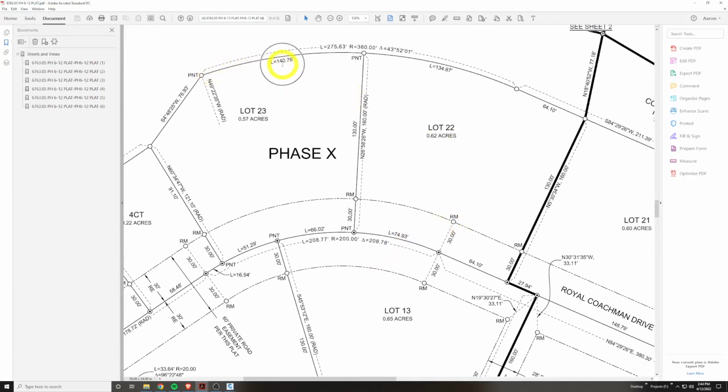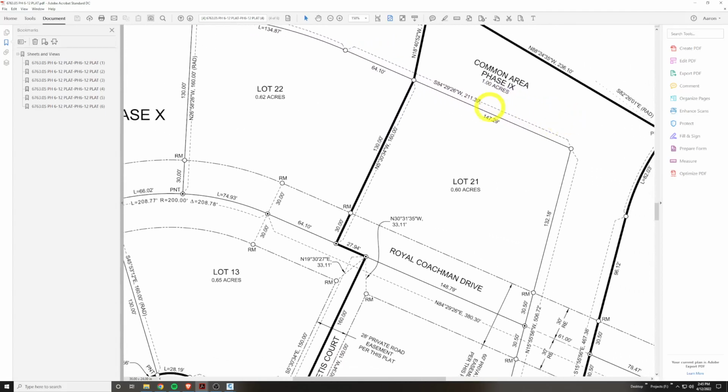Here we have another arc with 2 parts inside of it that make a whole. Here we just have a line. This is overall the same bearing and distance. So bearing is the vector, but this is the nomenclature common to surveying and land surveying with the 4 quadrants, northeast, southeast, southwest, and northwest of degrees, minutes, and seconds. Usually no decimal seconds because it's almost too much accuracy by far for our modern equipment even. And a distance or a magnitude of that vector. So bearing and distance, some people call metes and bounds. That's this whole line of the subdivision.